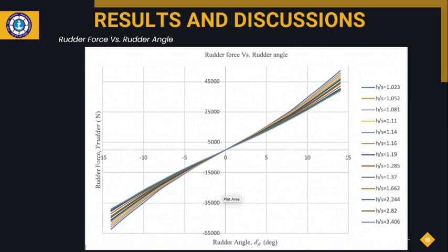For 14 degrees, we don't expect to have great non-linearities because the real rudder stall angle happens at nearly 35 degrees. But a numerical simulation using RANS has to be restricted to 14 degrees. Yes, we did go beyond 14 degrees, but it gave us a drop in the lift because of the limitation of the RANS solver to capture such high flow separation. So for our initial studies using RANS, we had to restrict our angle to 14 degrees. So I wouldn't say that we have been able to capture all the nonlinearities, but yes, we did capture some of the effects.